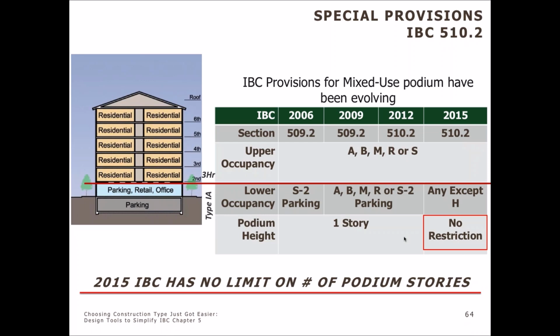However, keep in mind that the overall building height is still measured from grade plane. So there is a trade-off there. You might have heard people describe these types of buildings as 5/1, 5/2. That's typically talking about 5 stories of wood frame construction over 1 or 2 stories of podium.